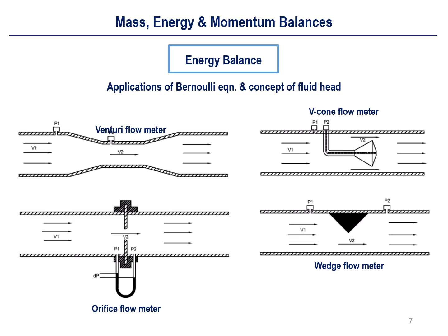And lastly, we have a more simplified version of this orifice. In this case, it is called the wedge flow meter. We have just a wedge here. Okay, so there is some blockade of the upper flow, and they are just forced into the lower part. So that's why we have the higher velocity. But we will also have some kind of divergence right after this wedge. So it has the same operational principle as the orifice.